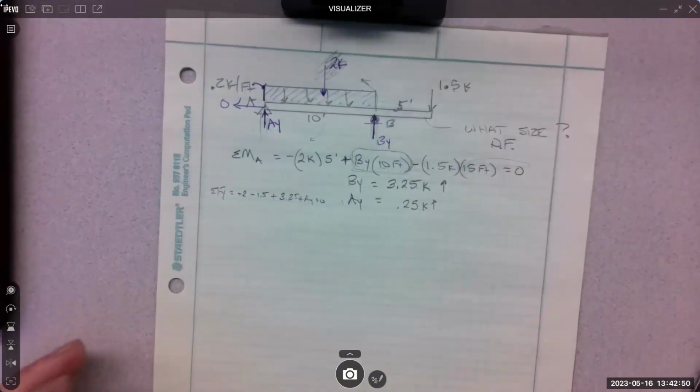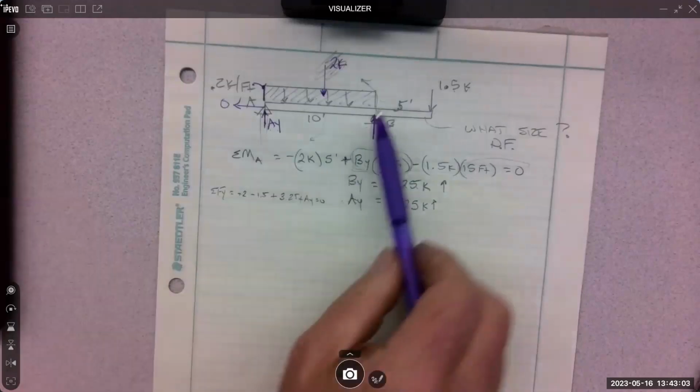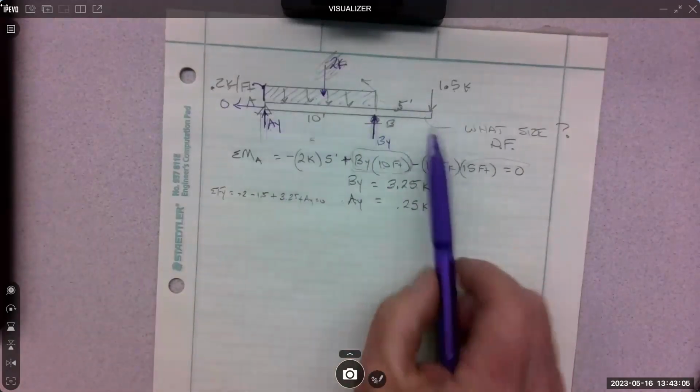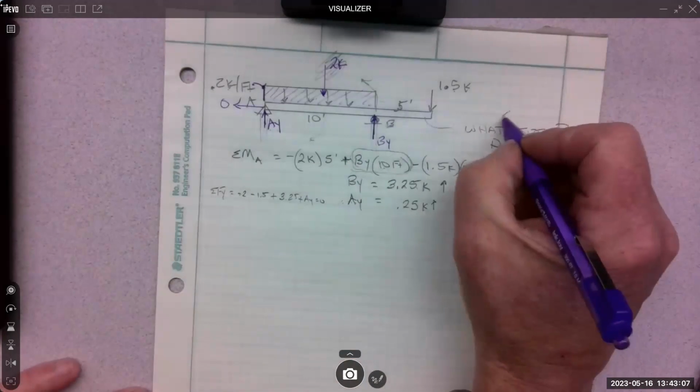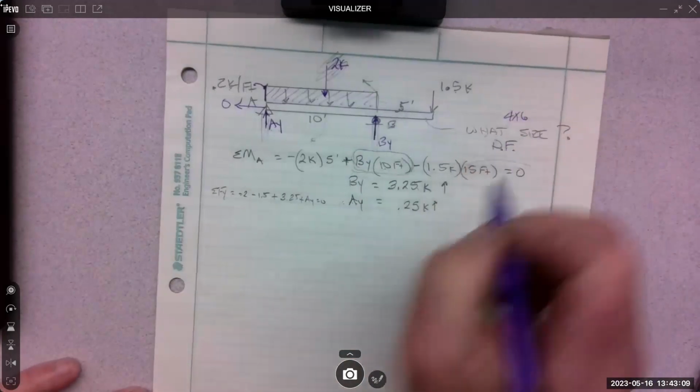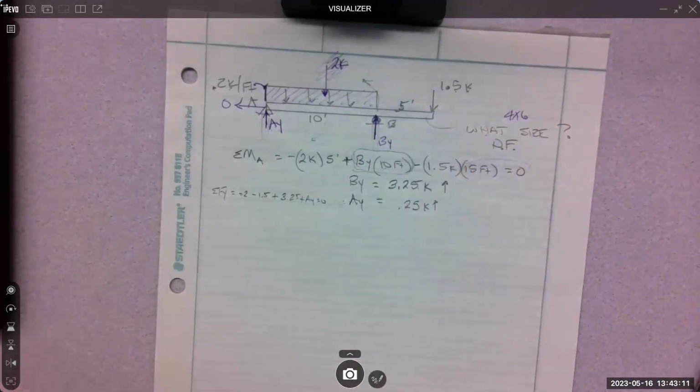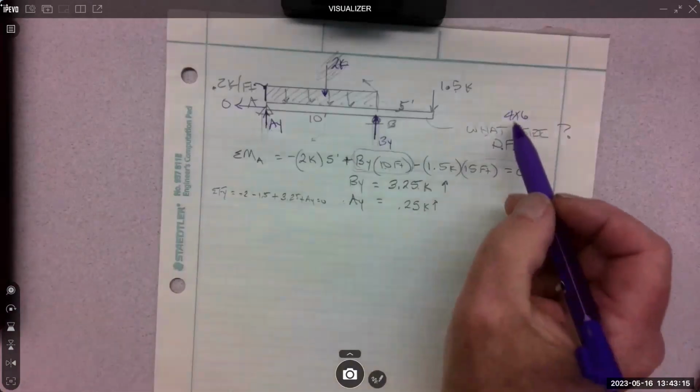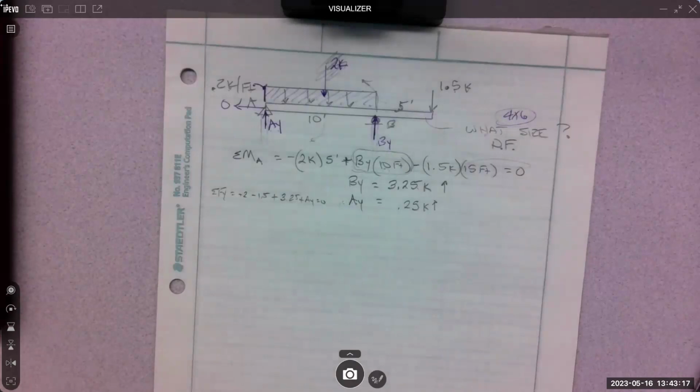So when we're doing beam design, this is kind of beam design, a little bit beam analysis. It's analysis if you know everything. You're just analyzing the situation, right? If we knew the load and we knew this was a 4x6 Doug fir, then that's just analyze it, right? So if you don't know it's 4x6, then it's a little bit design, like, oh, we have to figure out how big to make this thing, right?